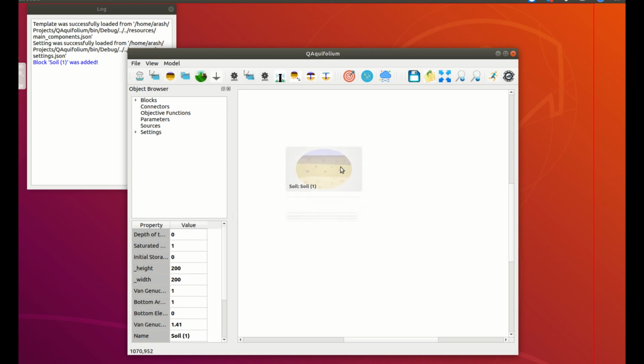So this is what I'm going to assume. I'm going to consider the groundwater table to be 2 meters deep, and then I'm going to use 5 soil elements to model infiltration. So each of the soil elements is going to be 0.4 meters. Please note that the units we consider do not matter as long as all our units are consistent.